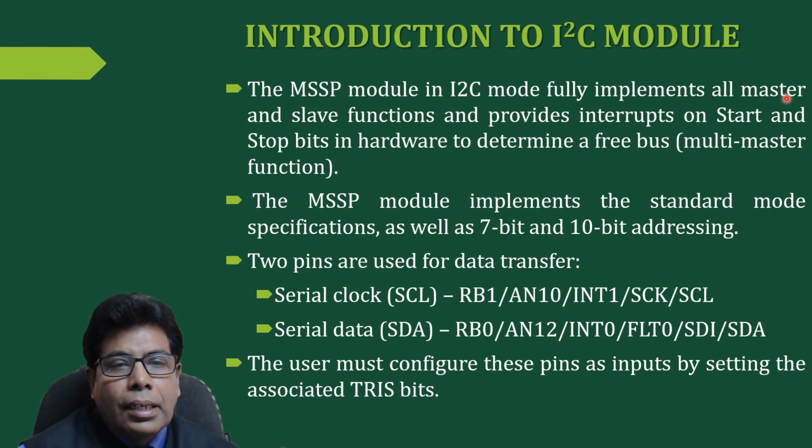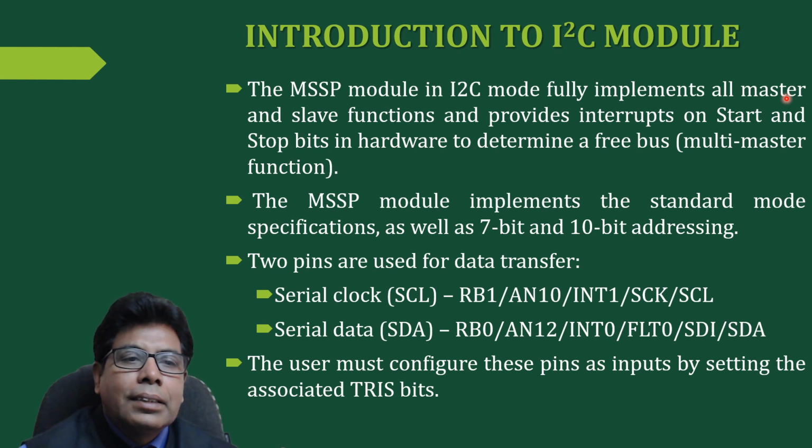Introduction to I2C module. Now the I2C module will fully implement all master and slave functions and provide interrupt on start and stop bits in hardware. So then once start and stop bit interrupts, will be able to determine a free bus in case of the multi-master function. In the multi-master mode, we'll have to determine a free bus, then only the communication will be possible.